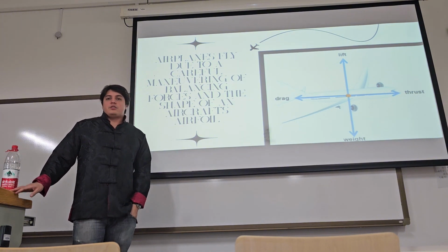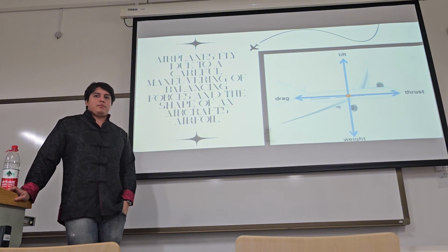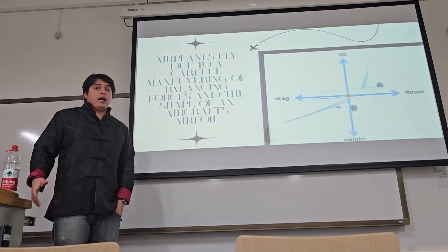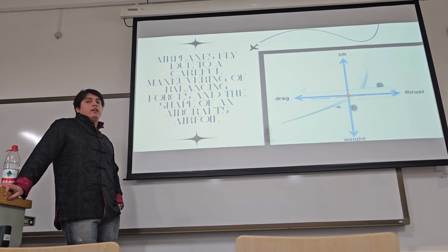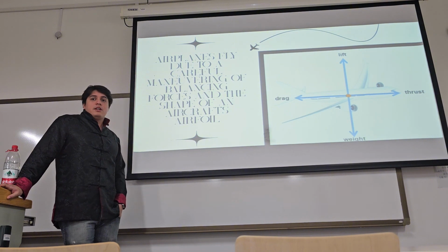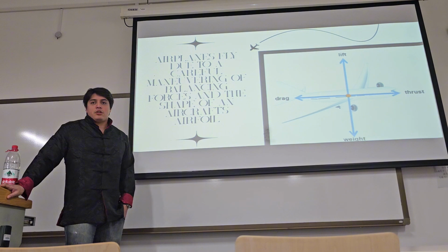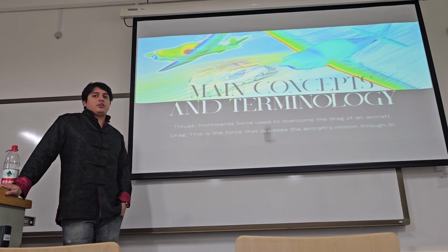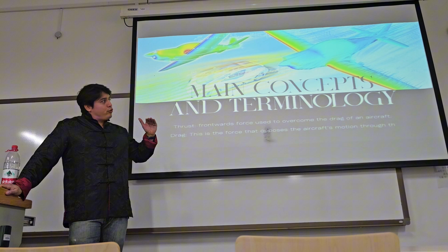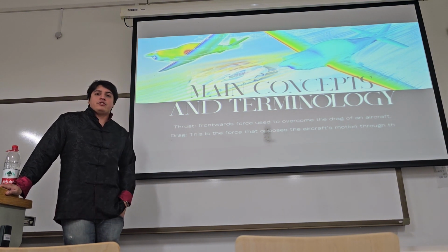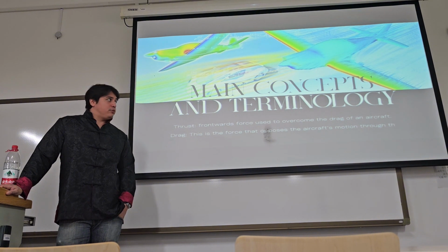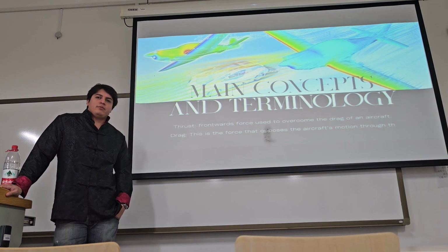So this is basically due to the different airfoils creating different results when interacting with the air. Today, we can explain what happens as the difference of pressure between the lower and the upper part of an airfoil surface. Simply put, the air particles that pass through a longer convex surface take more time to come into contact with their counterparts that slide through a shorter, more flat path. This causes a pressure difference, and adding the thrust provided by the engines, this creates the desired effect for an airplane to be able to fly. We can explain this phenomenon with Bernoulli's principle,